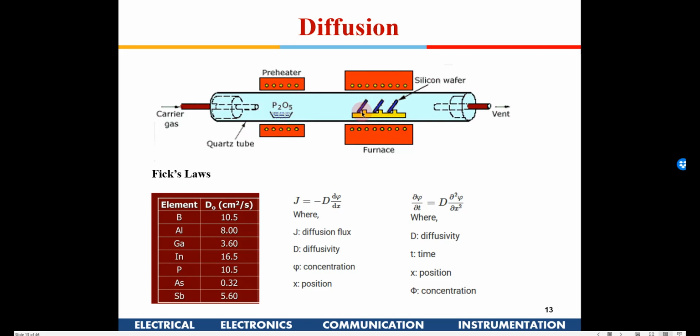Only in those areas these dopants will be diffused. So please do remember, in each of these processes it is done after photolithography. It is not that these molecules go and sit all over the surface, only wherever it is exposed. For all these processes, before we do the diffusion, the proper masking is done. Lithography is done, and windows are cut open where these things go and get deposited. That is known as diffusion.